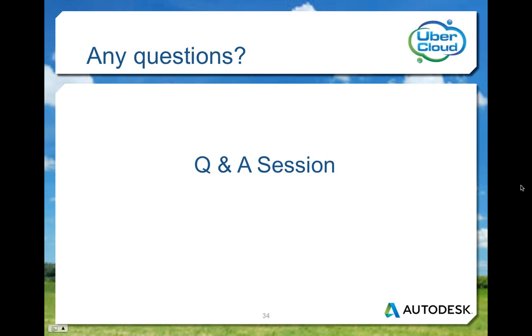Okay, let me turn back to Mark on this question here. It's coming from Doug. Doug says, how does time versus mesh size scale function in this application? Did you have some experience around that? Well, yes. Again, it's hard to be quantitative here, but there is a considerable increase, using default settings. I think the default is 3 layers of mesh at the boundary walls of the fluid.